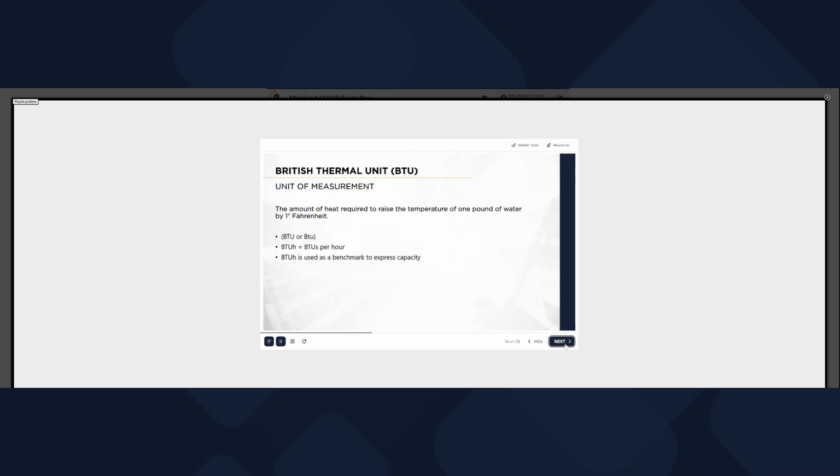BTU stands for British Thermal Unit. BTU is a unit of measurement. You should memorize where BTU comes from, as it's a common test question. It's the amount of heat required to raise the temperature of 1 pound of water by 1 degree Fahrenheit. You will see BTU written out with all letters capitalized or lowercase. BTUH means BTUs per hour. BTUs per hour is used as a benchmark to express capacity.